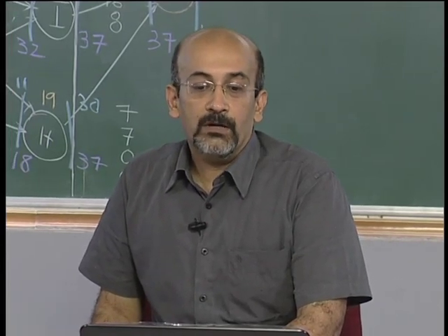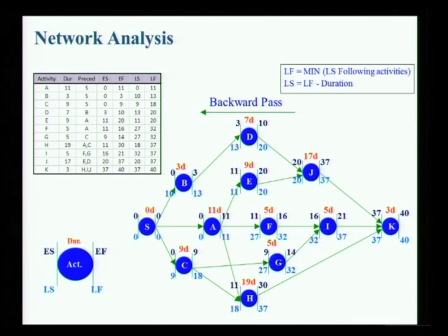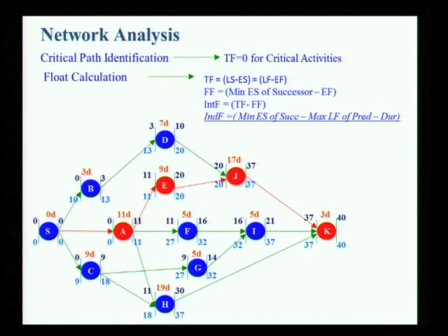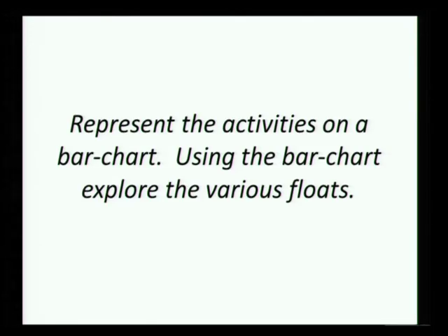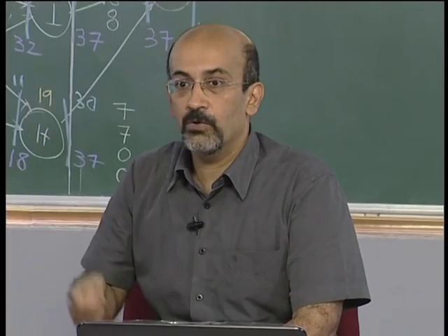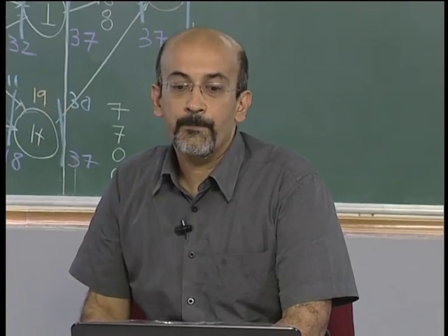Okay, so this is what we had wanted to fill up, and you will find that all the calculations we have done are in these slides. I am not going to go through it in detail, it is there for the record, and we have gone through the critical activities and all of the calculations which are associated. Now what I would encourage you to do is to use a bar chart to draw these, not now, I don't want you to do it in class, but you'll have to draw this and see if you can visualize the various floats we are talking about.